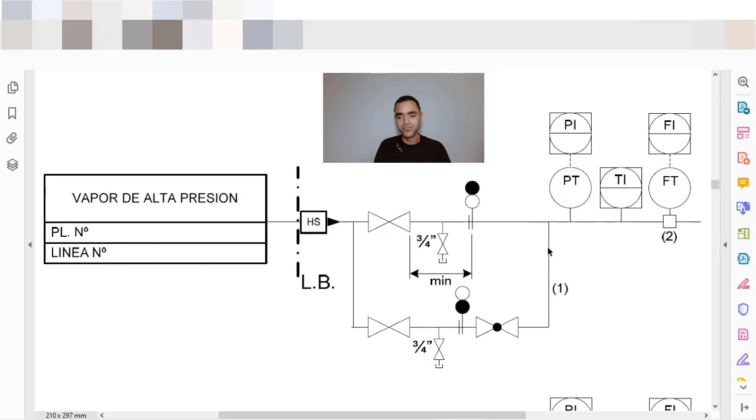There is a heat exchange between the vapor and the metal and the ambient condition. And once it is pressurized, and you will verify in the manometer or in the pressure transmitter that is installed in the field, once this is pressurized and the pressure is equalized, you will close the bypass drain, which has condensate formed here, and will open the main isolation valve.